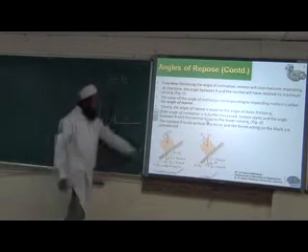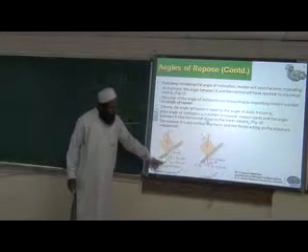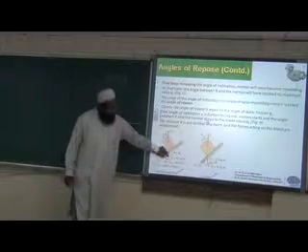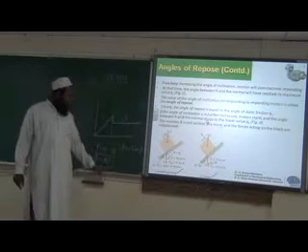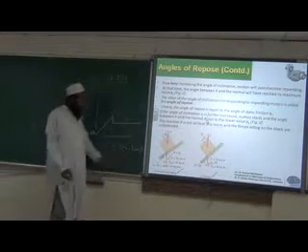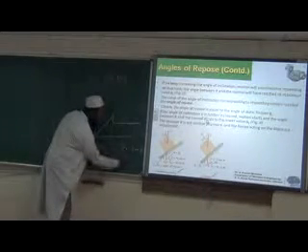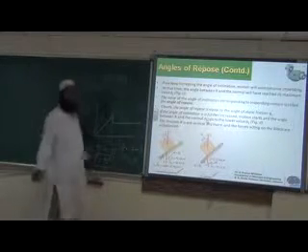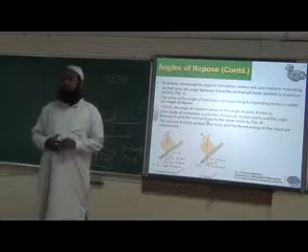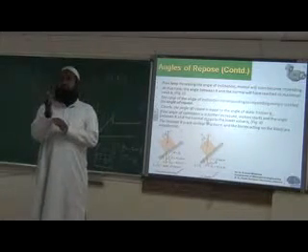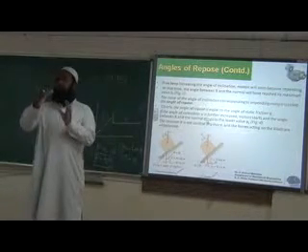If you consider the block, okay, so the resultant force has some angle with the normal. The angle between the resultant force and the normal is called angle of friction. And this angle of friction is also equal to angle of repose. If you consider the body on an inclined surface, how much inclination we can have to keep the body at rest?